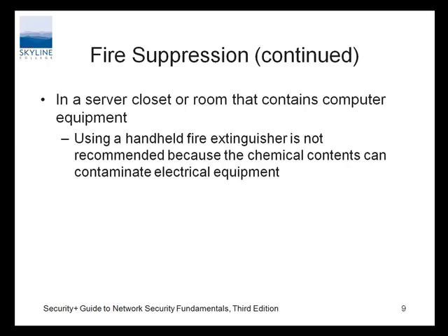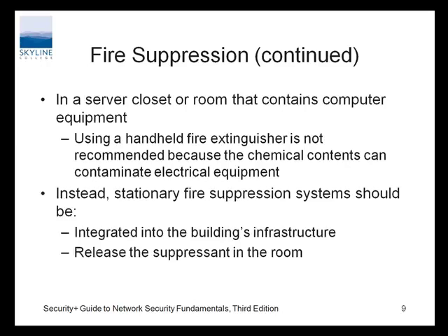If you leave the power on these things and they're still arcing and sparking, it's just going to keep going. The CO2 is not going to stop that. But it will do the cooling, and it will put out what is going to wind up being the residual fire.